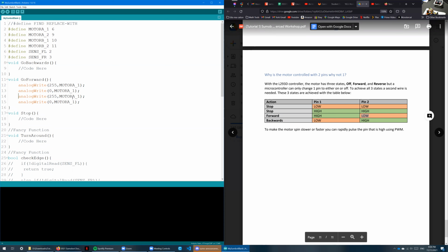which is just motor B. Oops, you know what I forgot? I forgot to add the little 2 there. Motor B2. And then that will also go in allegedly the same direction. I have no way of confirming that because I haven't checked the direction of these motors. Hopefully it'll go in the right direction, but we'll test it, of course. And it's very simple to tweak: if one motor is going in the wrong direction, we can just copy and paste that 255 and then change this one to 0. And if both motors are heading in the wrong direction, we can just change both of them from 255 to 0 and then to 255 here.